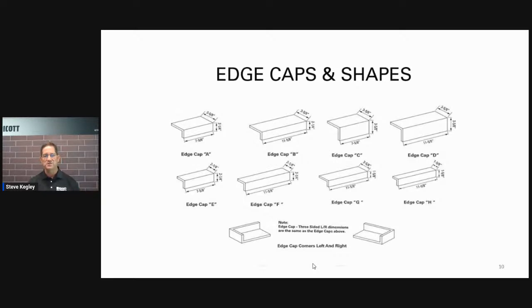So just be very specific and make sure that in your takeoff, you order enough material, and always allow for industry standard, which for brick is about 5%. Okay. If you're getting into something really unique or special, you might want to fudge a little bit and get a few more pieces than what you actually need just in case. But a good practice there is to make sure you order enough.